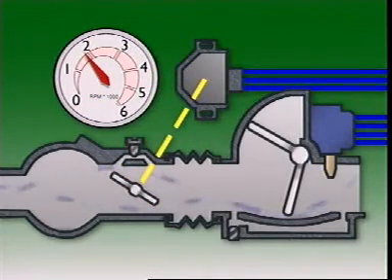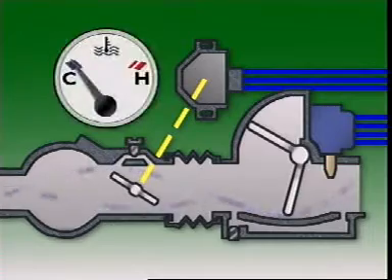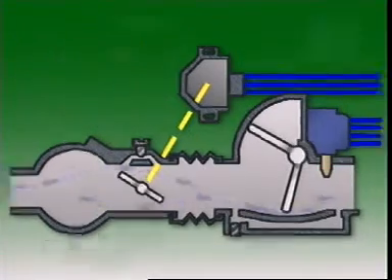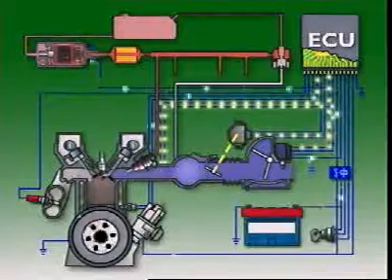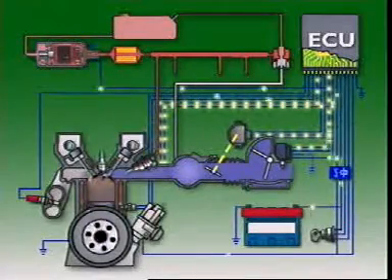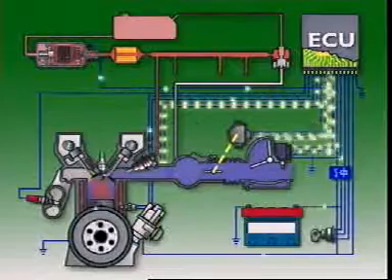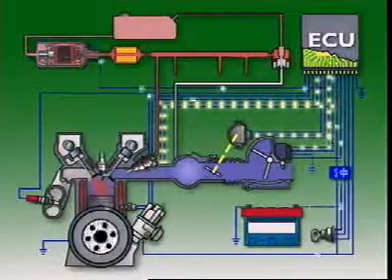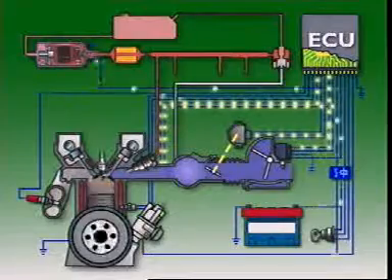Engine speed is in the low to mid-range. Coolant temperature is still below normal. These factors combined produce a fuel setting. It is less than if the throttle were opened suddenly for acceleration or to overcome increased load. However, it is more than it would be if coolant temperature were at its normal level.